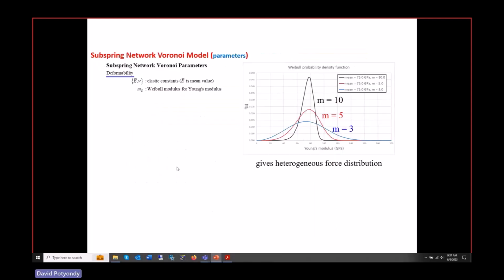This then allows us to build up a model, and here's the model that I have built up. And these are the parameters. This is the Cadillac of all models because it has a huge number of things going on in it. This is the model I said that is matching all of the characteristic stresses. This is the first time I've ever seen any bonded particle model match all those stresses. The high level description, these are the parameters for the thing. So these are these elastic constants at every single contact.